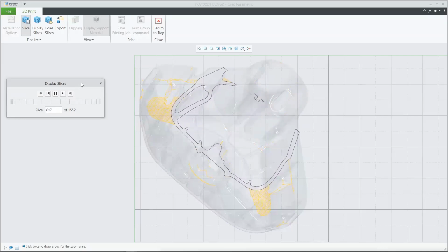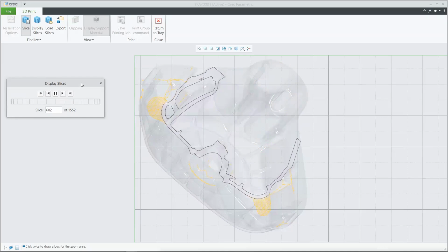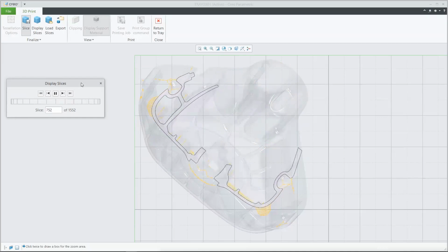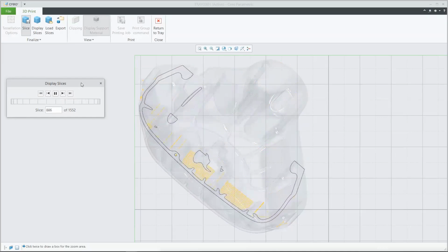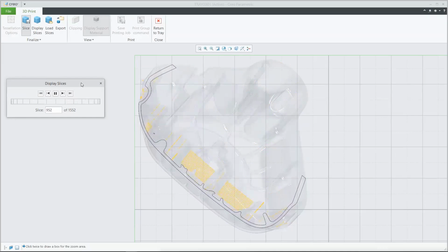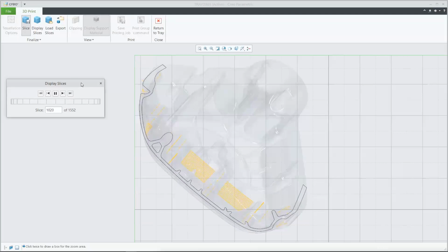And that's really one of the biggest things to notice throughout every step that we've taken in this entire process, is that it's right inside of the same interface, right? Whether it's for building out your lattices, starting from maybe a fairly standard, simple part, be able to do your preparation for 3D printing, do it all right from within Creo, right? You start with the base model, optimize the build direction to cut down on the use of support material. You can set up and connect your model into your particular printers, generate and edit the supports, the slice file, really everything that you need from that 3D printing process, you can just do right here from within Creo as well.